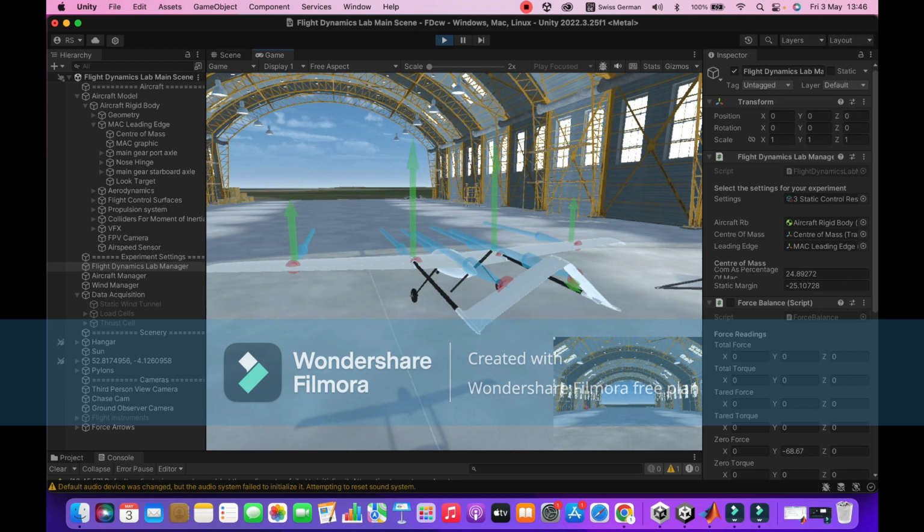The positive rudder deflection is achieved by pressing A on the keyboard, and it results in changing yaw to the left. Similarly, a negative deflection is achieved by pressing D. Now we check the flaps down and flaps up motion, and lastly we check if the throttle is working, and we can see the throttle starts spinning.